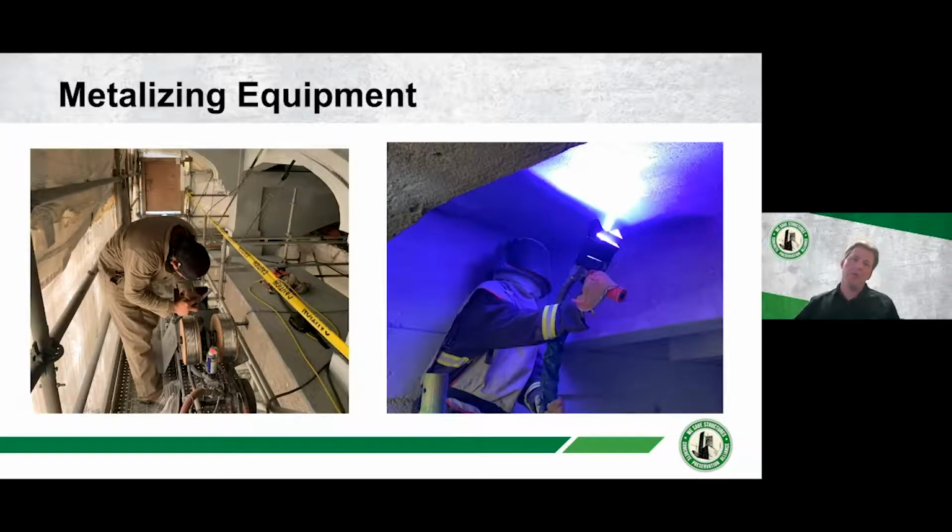So the metallizing equipment, this is a bridge master, and we have two spools of zinc wire on that bridge master. Each spool weighs around 60 pounds and is 3/16 of an inch in diameter. The reason why we have two spools is we have two lines. We have one wire running in one line, one wire running in another. Both of those wires meet at this tip.